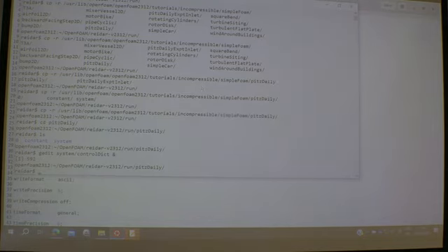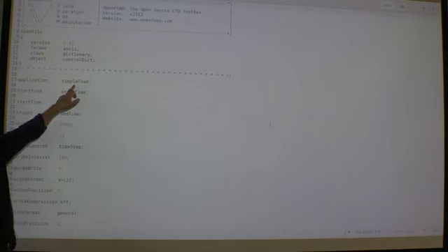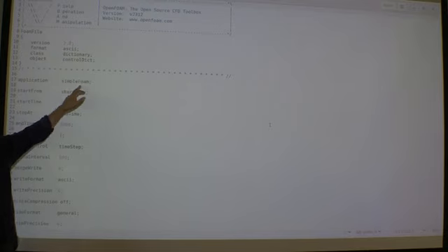And the control dict for this case looks something like this. As an application name here is called simpleFoam. Depending on the distribution, it may be something else, but the program is actually simpleFoam. Never mind. simpleFoam, start from start time 0, end time 2000. That's a big number. And then look at the deltaT, it's 1.